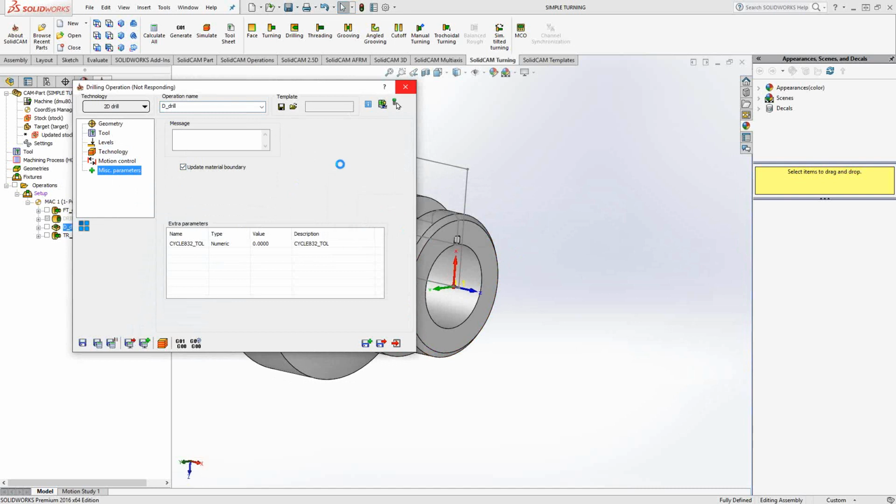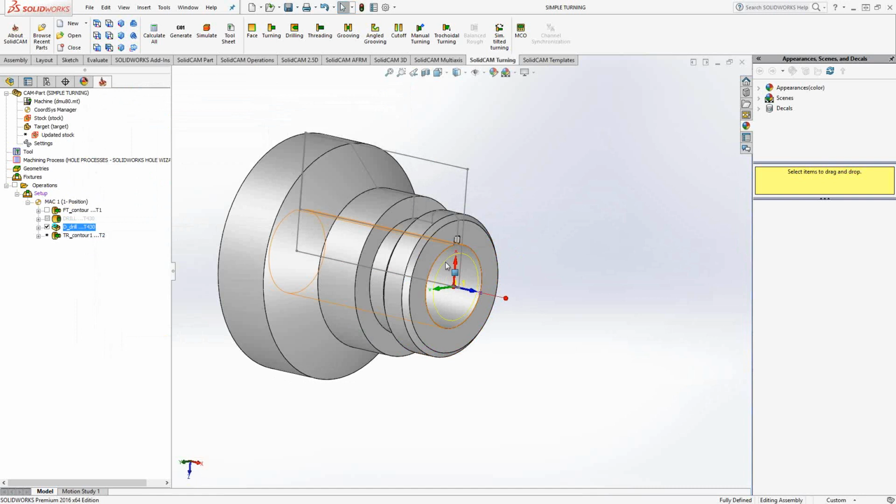Now, in many cases, a milling toolpath might be a pocket on the OD. It might be some sort of profile on the outside. Really doesn't matter in terms of a turned stock. But when you're doing drilling, it does tend to matter because obviously here we did a pre-drill with a live tooling rather than a lathe-based toolpath, and we want to see that update the turned stock.